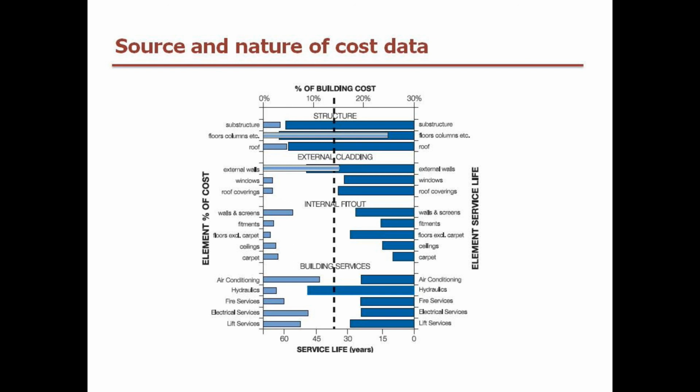Even the lives of commonly used materials like paint show some surprising variations, and are influenced by a range of factors. It could be the type of paint, the number of coats, the preparation, the environment where it is, or atmospheric conditions. It could be a seaside location, next to an industrial area, or a very trafficable inner city location. And the degree of exposure too, even to UV or rain.